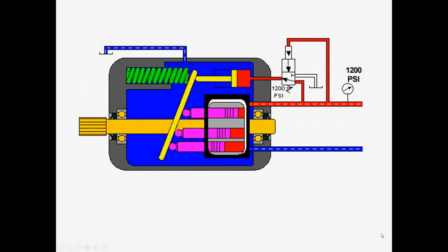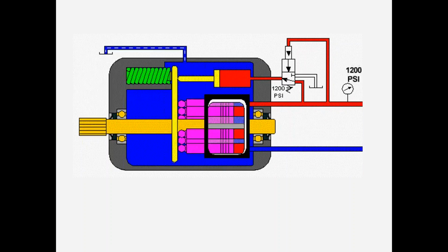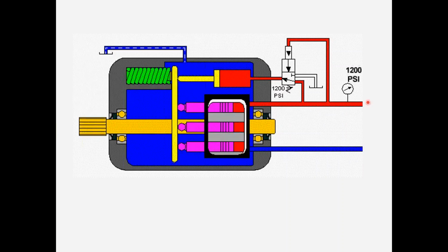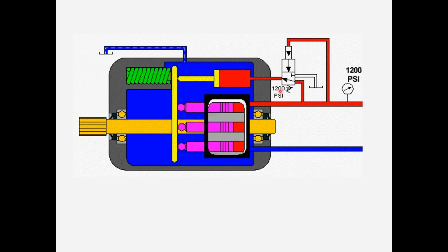And of course, if we block the flow altogether, we close all the valves, stopping the machine, but leaving the pump running, then the pump will fully de-stroke. And you see that the swash plate angle is full vertical. See that the pistons are not stroking at all, even though the barrel is still turning, the motor's still turning. The flow has been reduced to zero because it's currently blocked. The only thing coming out of the pump is whatever bypasses across the pistons, but it will maintain the compensator setting in the line.